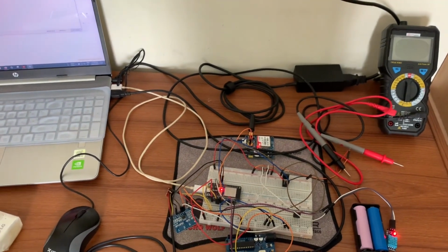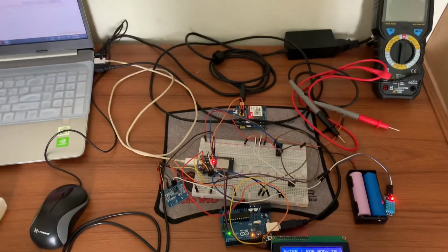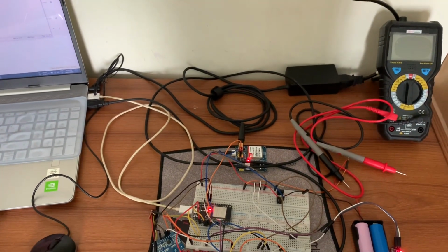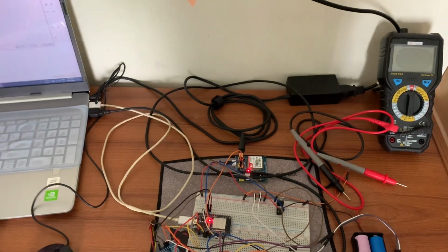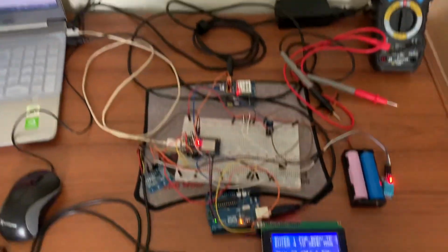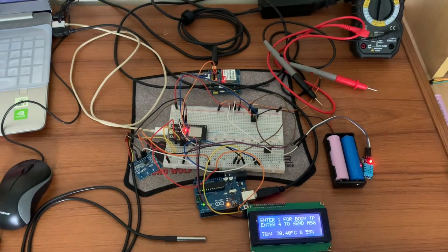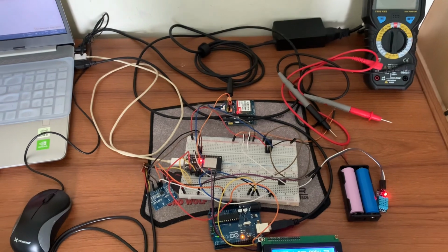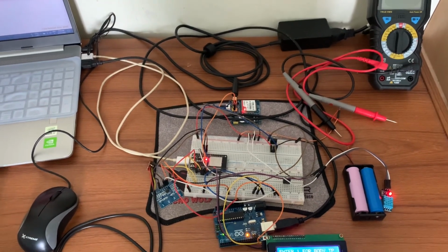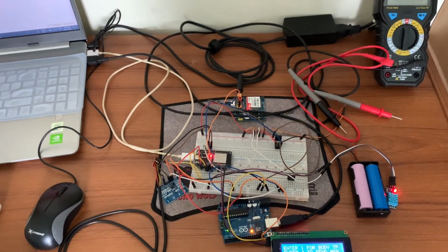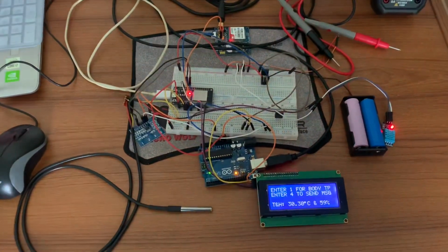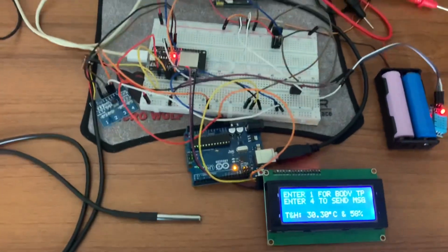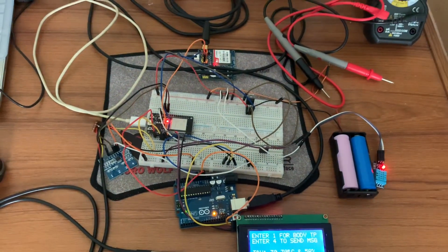So in order to store all these samples, you have to define an array with a buffer length of 100. If you define 2 such arrays, each will consume 100 length times 32, so 3200 bits for each array. That means 800 bytes, so 2 arrays will consume 1600 bytes. But the Arduino Uno board will allow you to allocate around 2048 bytes for global variables.